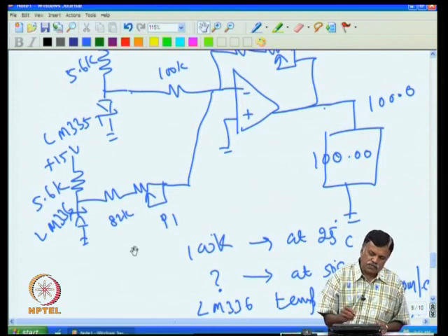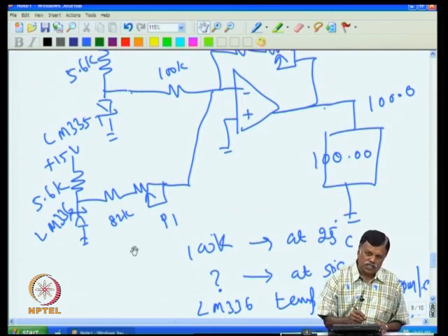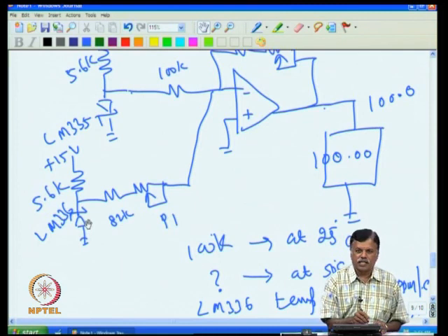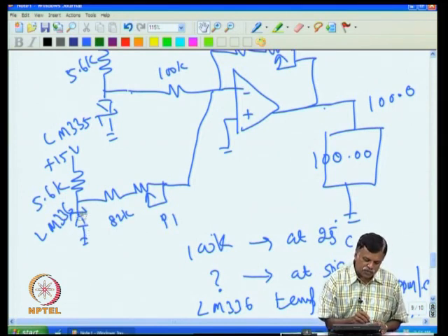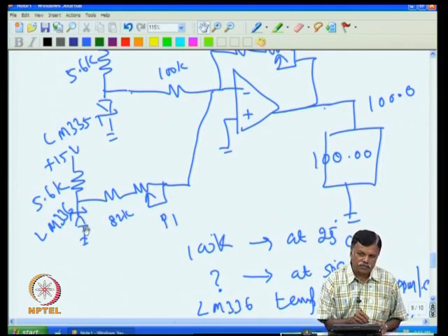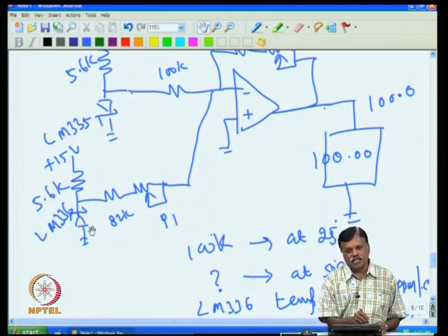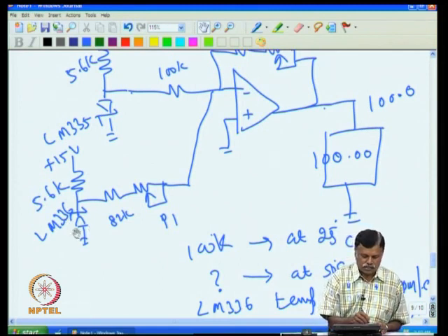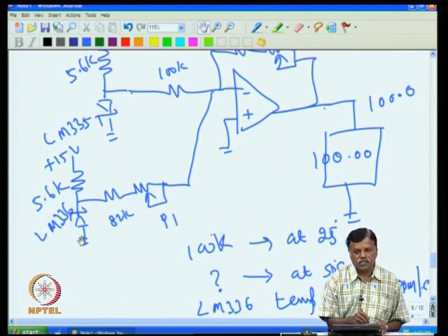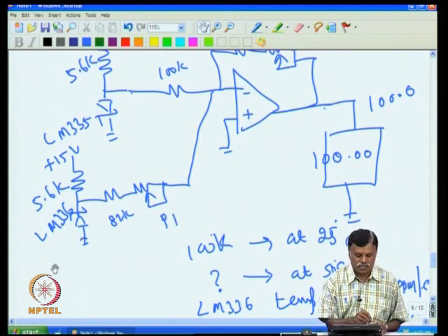So assume that for industrial grade equipment, in the worst case it can be minus 20 degree at the low end, and at high temperature it can go to plus 80 degree. That means up to 100 degree temperature variation is possible. I am not talking about temperature measurement, I am talking of the instrument's surroundings. So we know that this changes by 30 ppm maximum. That means for 100 degree, a 3000 ppm change in voltage is possible for the worst case temperature change.